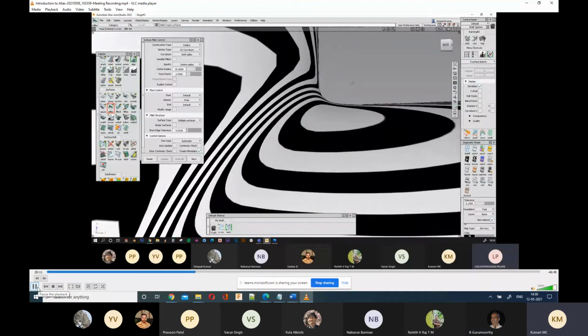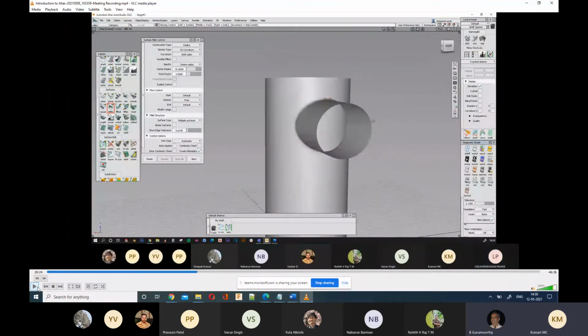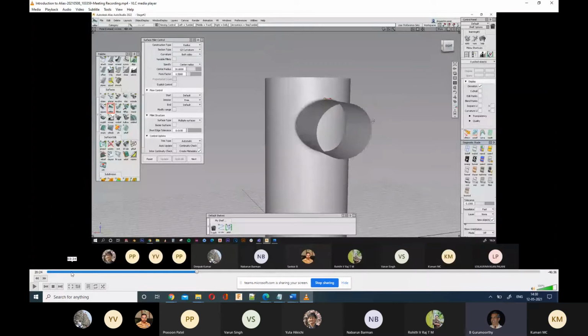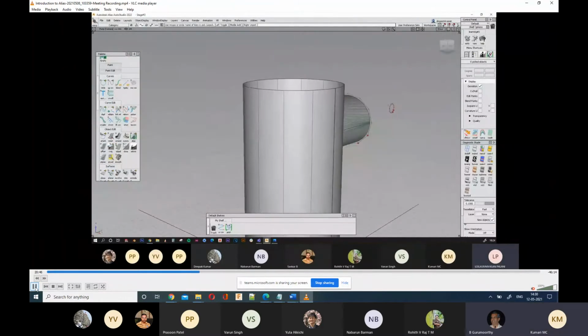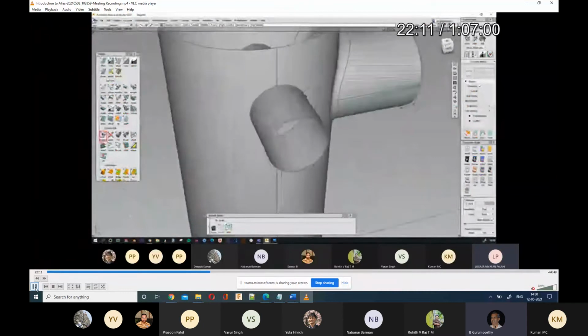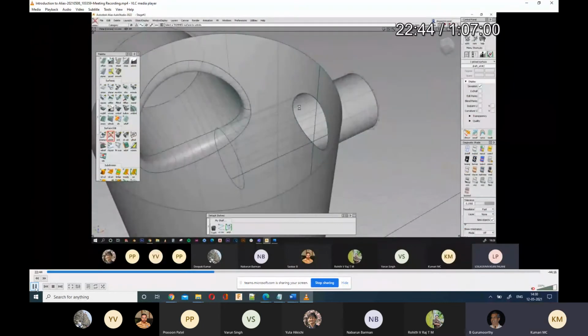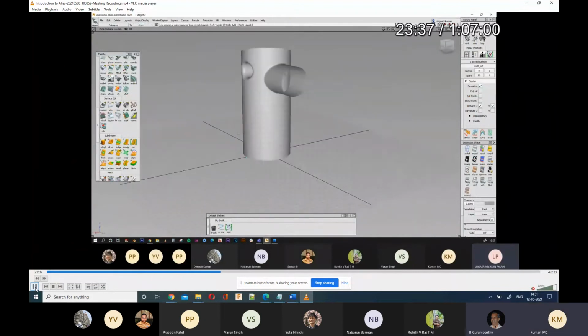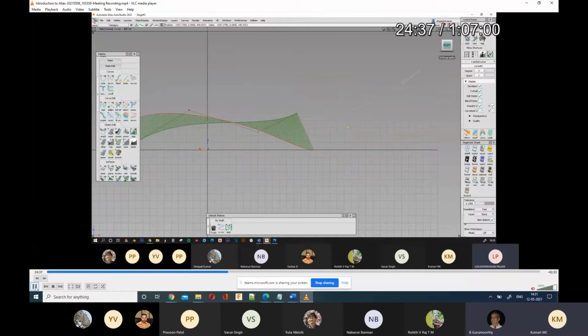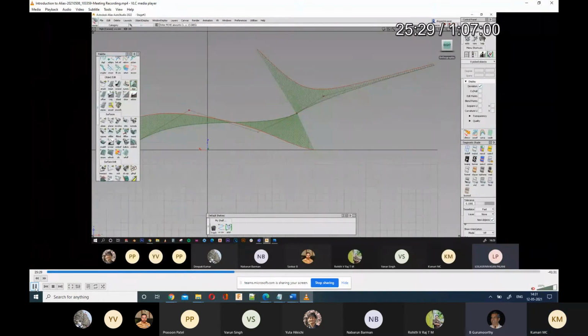So even with this curvature, you can see. Okay, so I don't know what the confusing part was. There are two parts here that he is talking about. The G2, G3 references that he is using are references to continuity. Meaning that if I'm looking at a differential property of the surface, it could be curvature, G2, or it could be G3, which is the next level derivative, then it will be continuous. That's the G-star part of it. The contour plots and what look like the zebra plots, and they are actually called zebra plots, that he showed you have to do with the quality issue. Okay.